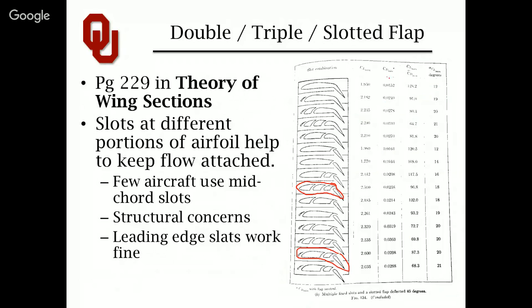Now also look at what happens to the drag coefficient. So it's just a plain deployed flap. You have a lift to drag ratio in this configuration of 128.2. Keep in mind, that's just the airfoil. My goodness, if we could achieve that on the whole airplane, we'd burn way less gas. But with these different configurations, you pay different penalties in overall lift to drag ratio, which is something to consider whenever you deploy flap systems. It's the same reason you don't want to cruise around the sky with them, because they generally increase drag significantly.